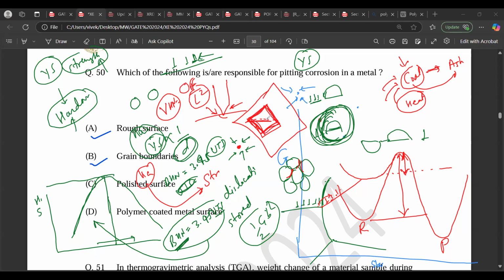To do any deformation, whether at the micro level, macro level, or micron level, the dislocations need to move so that you see plastic, permanent deformation, whether it is just a small indent or a big plastic deformation. So you have already forced the dislocations to move, and if the dislocations move, they will entangle, right?